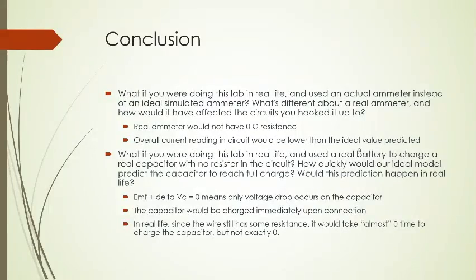In conclusion, what if you were doing this lab in real life and used an actual ammeter instead of an ideally simulated ammeter? What's different about a real ammeter, and how would it have affected the circuits you hooked it up to? A real ammeter would not have zero resistance, and therefore the overall current reading in the circuit would be lower than the ideal value predicted.